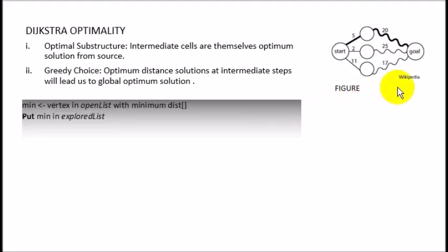Like we can show here with an example. Here we have three choices. The program makes the choice with the minimum value, so we would go here. Now this cell will update its neighbor. The neighbor of this cell happened to be the goal. So the goal value would be set to 27. Now the program again runs and finds the cell with the minimum value.